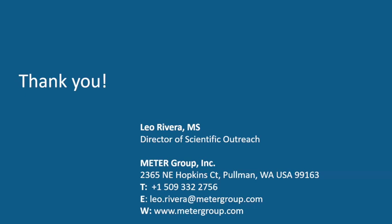That's an interesting concept. We use the same methods that you do at Acclima. We do the water to air, the air to water measurements. But we've noticed that the main factor that influences the sampling volume is the conductivity of the medium. The attenuation of the electromagnetic field is a big factor. And if there's conductivity present, then the field goes way down. So even more than with moisture content. So that's another factor that needs to be taken into consideration.